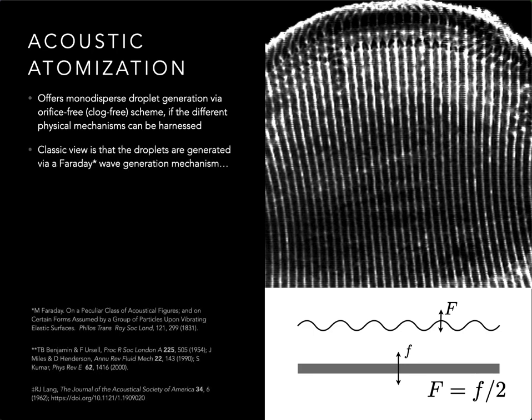The classic view of acoustically driven atomization is that the mechanism is a parametric mechanism, or what's called a Faraday wave generation mechanism. At right is an example of a fluid interface where there are capillary waves appearing as a consequence of excitation. Michael Faraday, back in the 1830s, discovered that if you shake a pie tin at a given frequency, lowercase f in the lower right-hand figure, then mercury sitting in the pie tin would show capillary waves that were one half that excitation frequency.